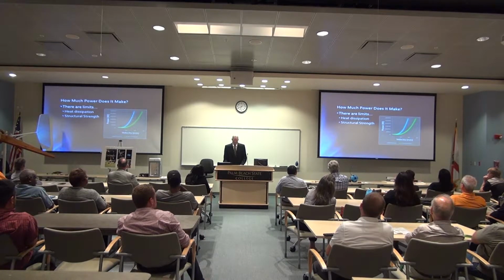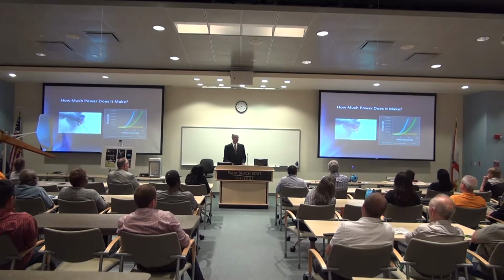So the first limit we come up to is the heat dissipation potential of this alternator. And that kicks in around 2,500 watts. If you try to have this thing sustain more than 2,500 watts for any given period of time, it will overheat and burst into flames, and that is a bad thing for your wind turbine. Definitely not anticipated behavior.